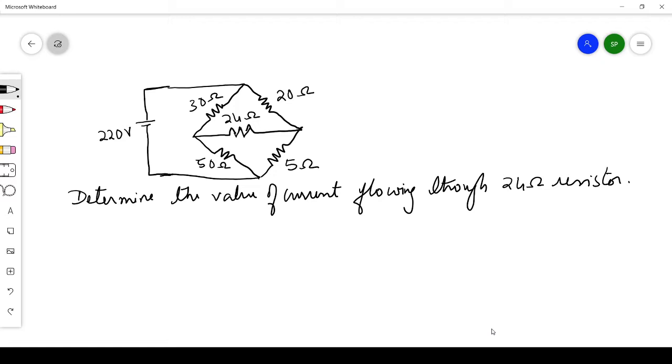Then the second step is to find the Thevenin equivalent resistance by removing the sources, looking into the circuit from those open terminals. That is the Thevenin equivalent resistance. Okay, now we'll see how to solve it. So step 1 is to find VTH, the Thevenin equivalent voltage.